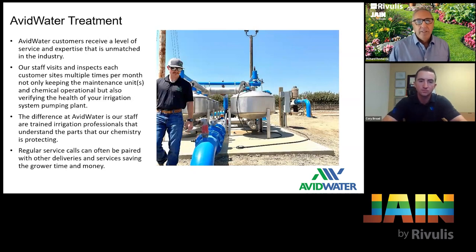Yeah, well, I love the analogy of blood pressure and pulse, right? It's pretty basic, blocking and tackling, or ground balls and fly balls. But we know what the norm is, and if it's off, you've got a big problem. Yeah, or hopefully it's a small problem, and then we can address it ahead of time. And maybe even conversely, the other way is, hey, your pressure is down and your flow is up. Yeah. Well, maybe you have a leak somewhere, or somebody left a valve on, or they're not running the system the way you think it is.